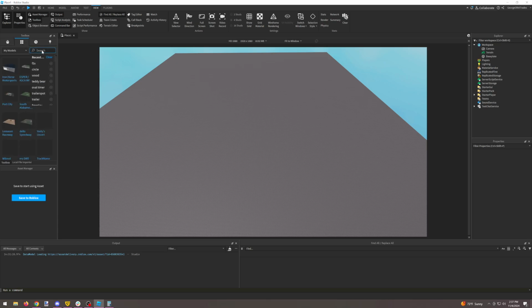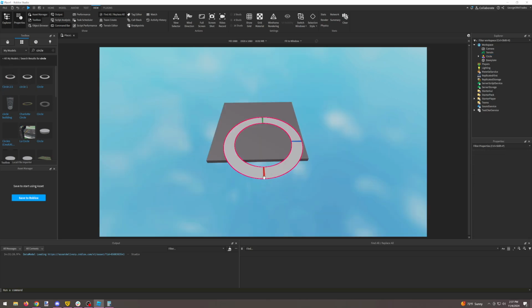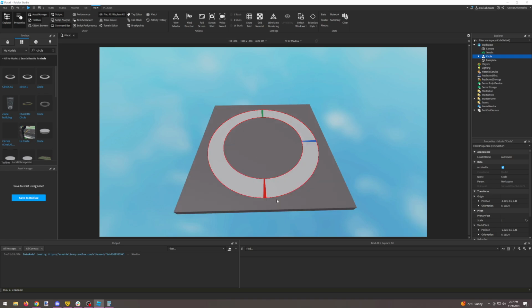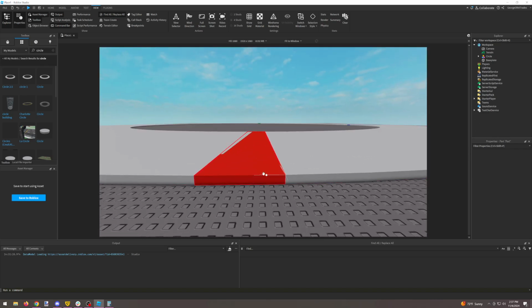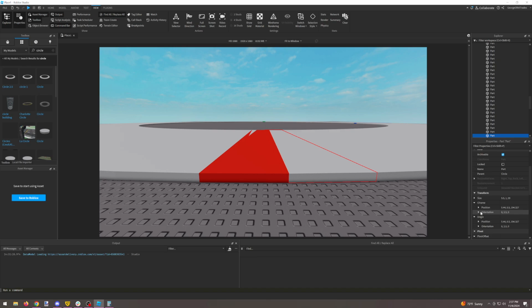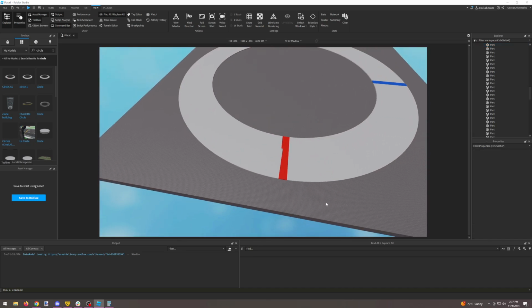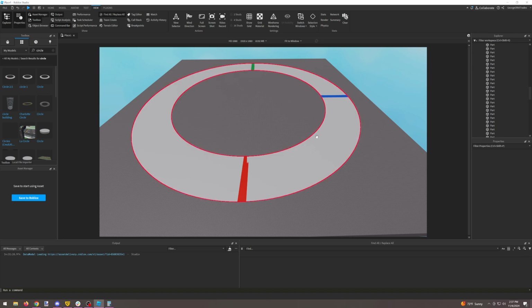Once you do that, we're going to bust out our circle. I will have these circles available in the description, but I'm going to use circle 2.5. What circle 2.5 is, is that each segment is 2.5 degrees of rotation from the next. So we can see here this orientation is 0, 0, 0, and this one here is 0, 2.5, 0. And each time these will go 2.5. That gives us a pretty good rotation around the corner in a pretty smooth format.